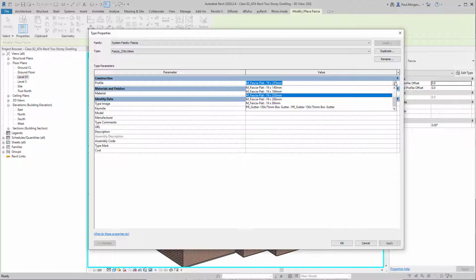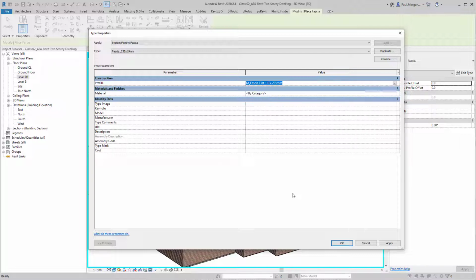So there's some defaults in here. You can see like 235, or you might choose 140 or 286, or maybe it's a smaller one that's only 89 mil. But you could draw your own and then bring that in. So basically this is almost identical to a sweep. It's just that the sweep profile is drawn in a family environment as a profile family and then loaded into Revit. And then this system essentially sweeps it on the elements that we pick. That's the best translation I can use.